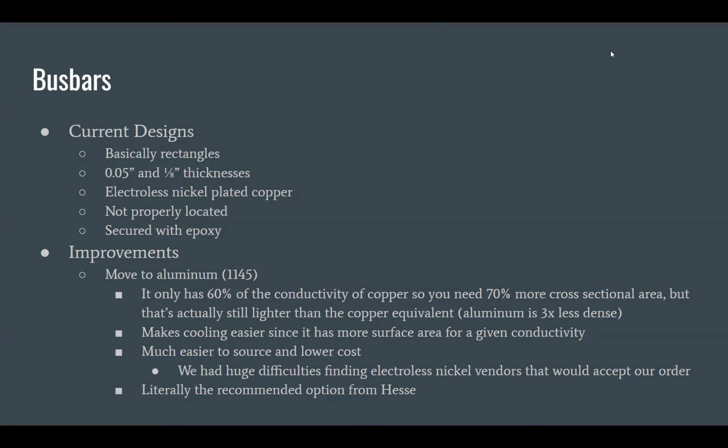When you mean cover up the whole space, like, the whole thing? Yeah. So that's one thing that actually, if you look at battery pack design, like if you go onto your phone and Google a bonded battery pack, you'll find really 2 sets of results. One will be the strips like you see us doing, and then another set where the entire surface is covered in available bus bars, and you just have these tiny gaps between them, and that's it. And so that's a relatively common solution. People go through and they'll basically fill all of the available area. So there we go. Yep.